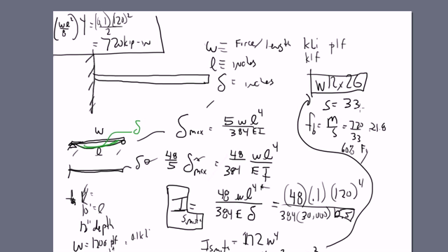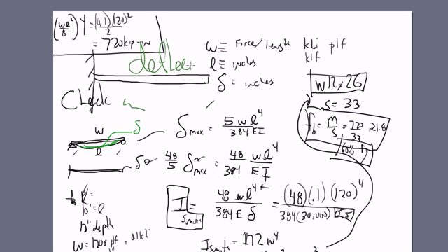And you have to, of course, check for both criteria, that the bending stress is less than some required or allowable stress, with that really not exceeding 60% of the yield stress, and also that the deflection fits within some criteria. So you always check, try to do the color here. Okay, so check, not the color, try it again. Check for serviceability or deflection and stress.